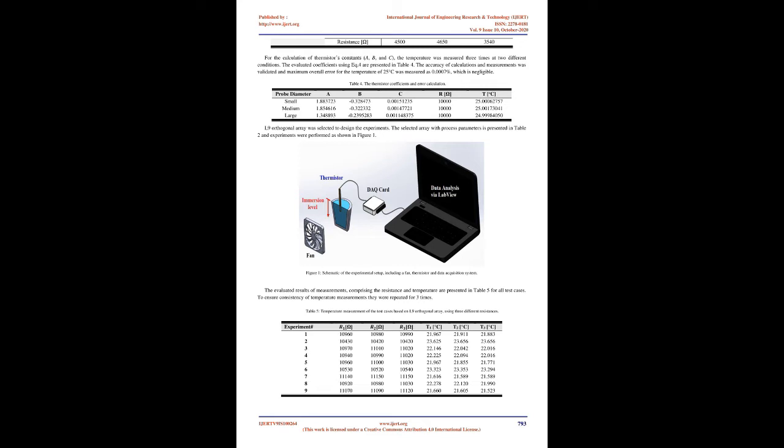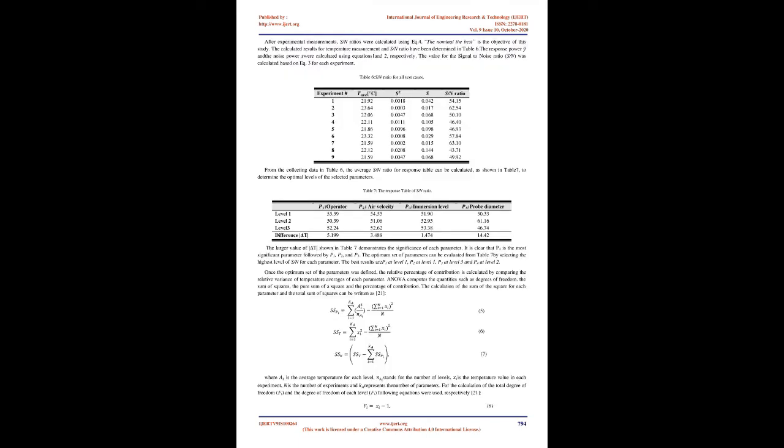Taguchi orthogonal array method is applied to optimize the measuring process and to achieve the best configuration of controllable parameters. According to the number of selected parameters and their levels, the L9 orthogonal array of Taguchi was selected, as shown in Table 2. According to the selected orthogonal array, the Taguchi technique decreases the number of experiments, which leads to a reduction in time and cost. This particular design of orthogonal array covers all parameters with a small number of experiments, allocates control parameters, design variables, to the columns of an array, and transfers the integers in the array columns into the real setting of parameters [17, 18].